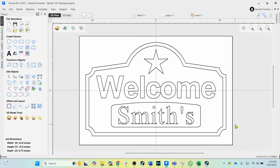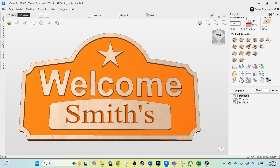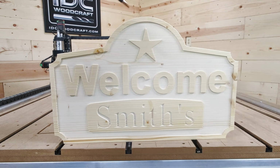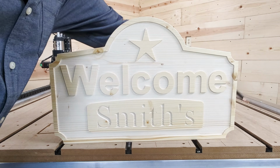Well, my friend, we're in the final stretch where you're going to take this project right here that you just finished designing and generate it to look like this in your design software. So the three toolpaths we are going to use are called Pocket or Pocketing, Profile, Profiling, and Vcarve. And here's what each of these toolpaths are. We have the outside profile where we're doing the cutout of the project. That is actually profiling, when we're actually following the profile of a line.